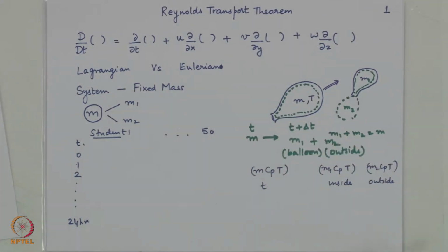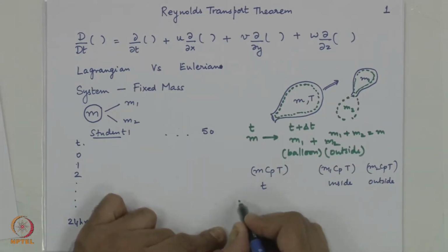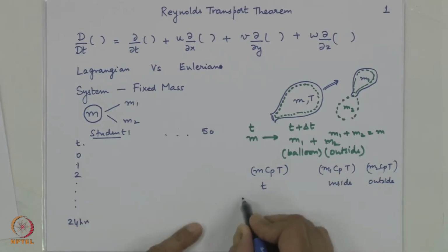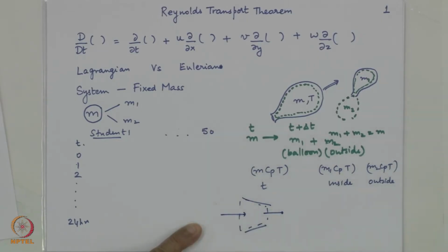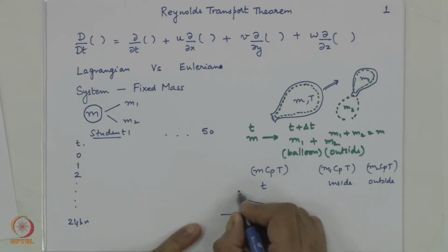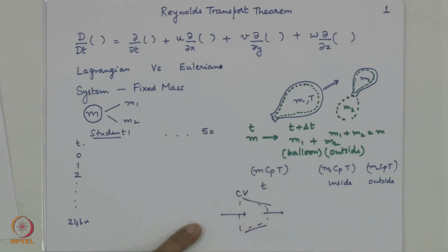But now in engineering that is not practical, because if I have, say, a turbine or a pump or something where the flow is going from the inlet to the exit, afterwards it goes to the generator and goes to the atmosphere. So, it is not practical to follow a fluid particle or a system. That is where the control volume analysis comes into effect.